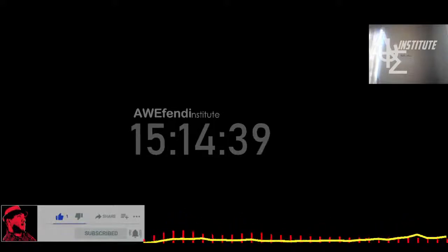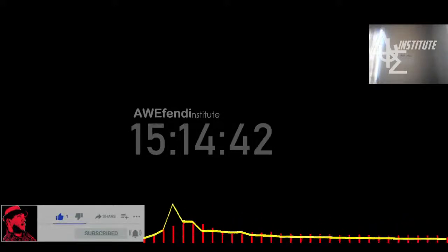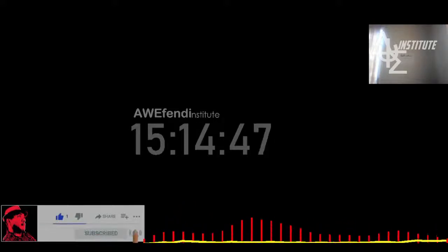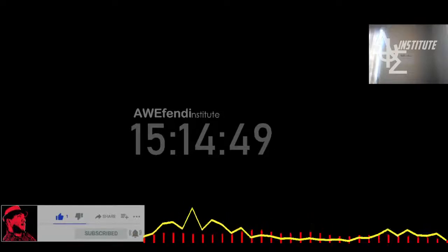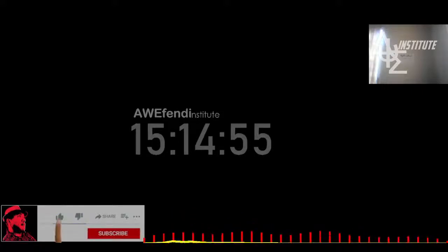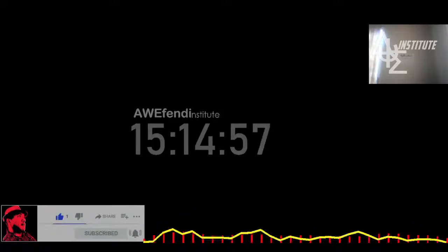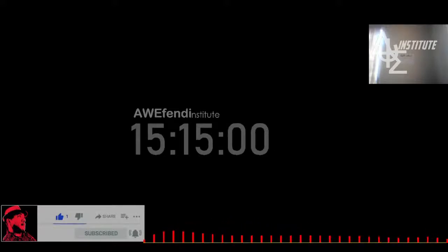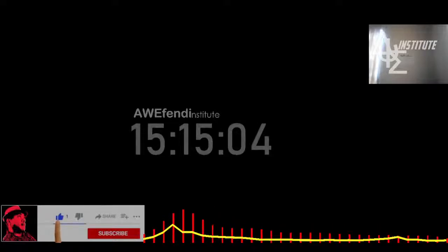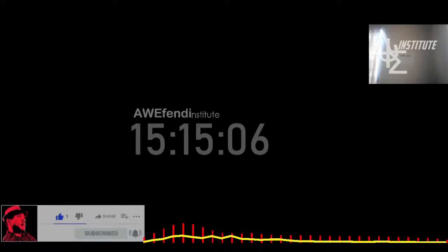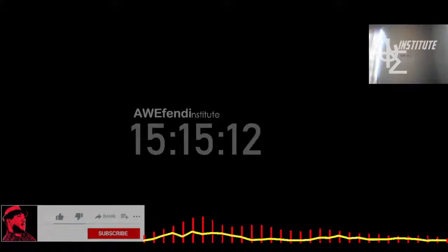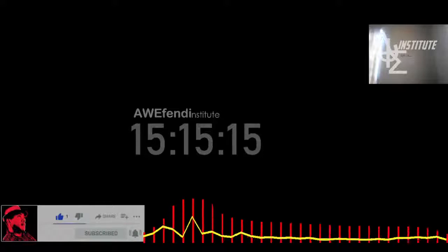We're at maximum temperatures of around 1,136 degrees Celsius, so way too hot. We need to cool this thing down. So what we're going to do is, if I hide these two components, you can see we have some cooling channels here. Basically, we're going to first extract the fluid volume, because we're going to simulate the fluid flow together with the heat in the solids and the heat exchange between the two, so a CHT calculation. So let's go ahead and extract the fluid volume.